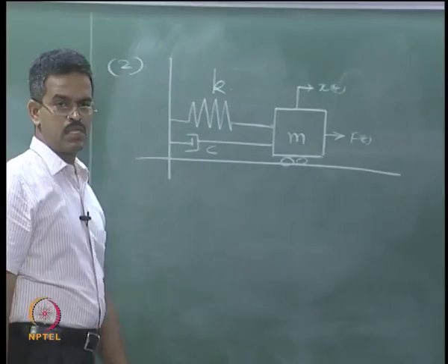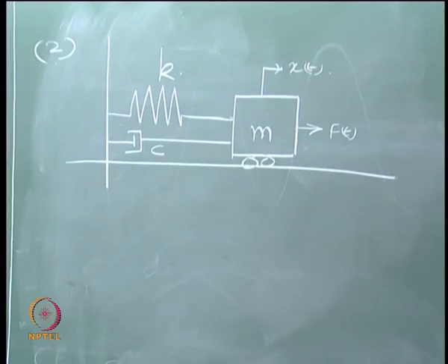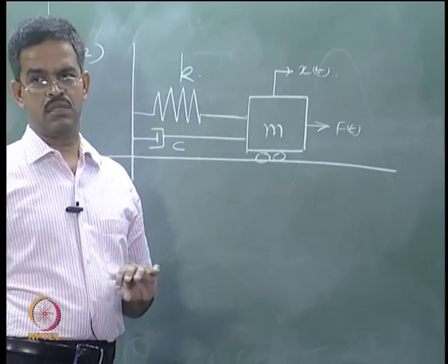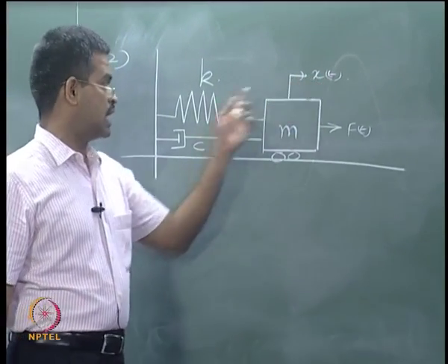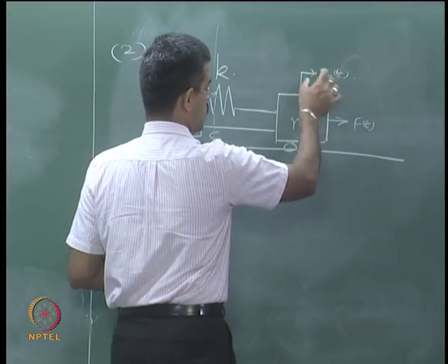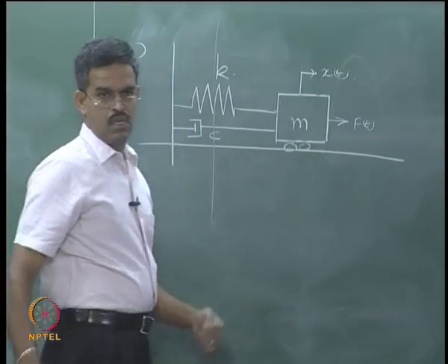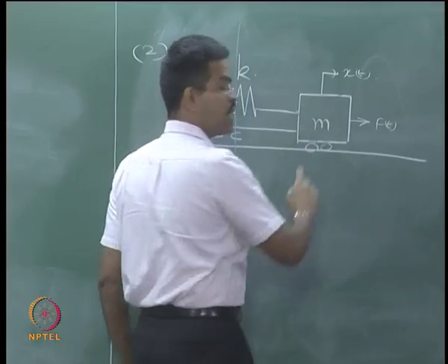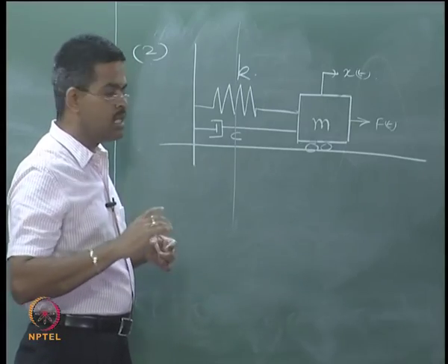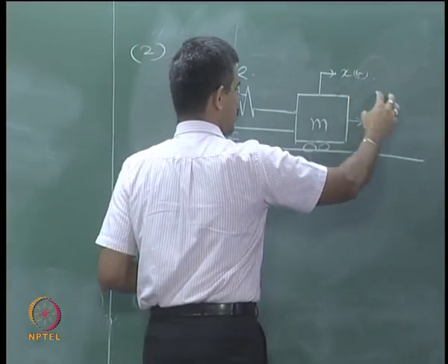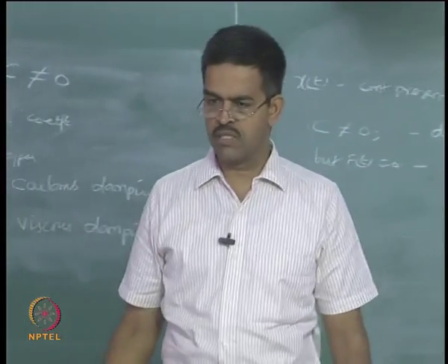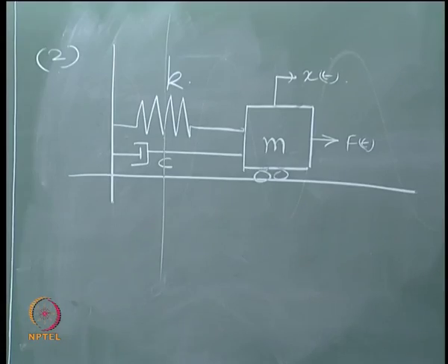You must understand there is a very great similarity in all the problems or all the derivations I am doing. I am measuring the coordinate of displacement of the mass only at the point where the mass is concentrated. I could measure the displacement coordinates anywhere at my origin, anywhere I can measure. Okay, I am not doing that. I am always measuring the displacement coordinates only at the CG of the mass or where the mass is lumped. I am also applying the force only at the point where the mass is. I can also pull the spring, I can push the spring from here, I can move the support, I am not doing them. It means in general I am using the displacement coordinates and the force coordinates at the point where the mass is lumped. Okay, that is a very important point. We will violate this and see what happens later in multi-degree freedom system models.